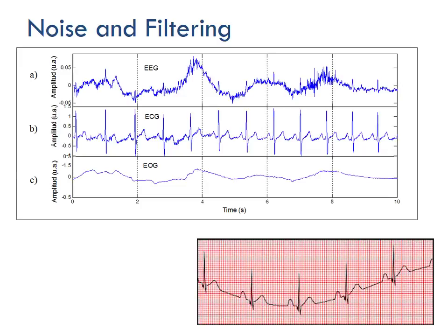And then finally we have EOG, electrooculogram, if I remember right. EOGs are essentially measuring signal from your eye. This is a way that you can do eye motion tracking and some different eye readings. You'll see that it's a very stretched out signal. That doesn't mean that there's not noise in there. There's a whole bunch of tiny little bits of noise. But in general, to me, it looks like a little bit cleaner of a signal. But there's also less pattern there, as compared to the ECG, which has a very distinct pattern, and the EEG, which has a very distinct high frequency pattern and a less distinct but still present low frequency pattern.